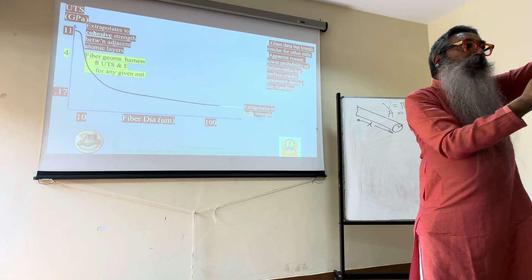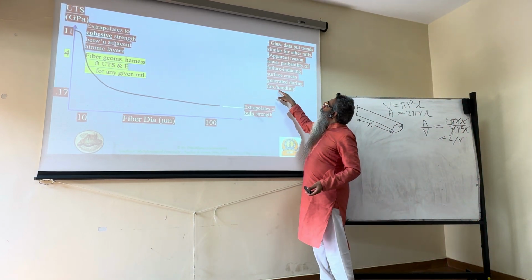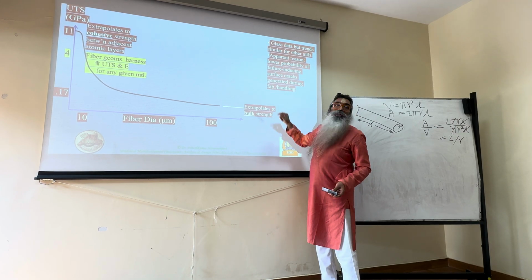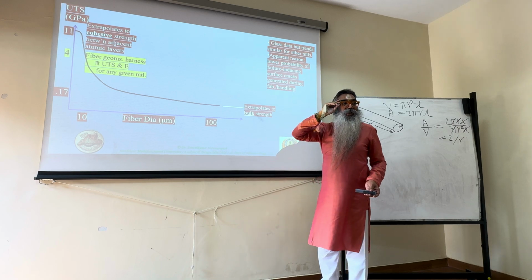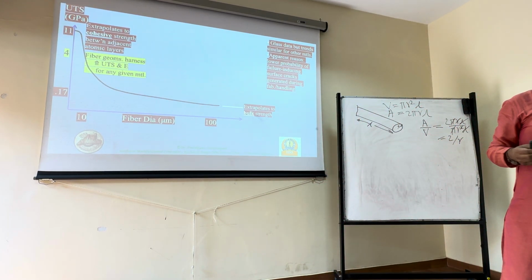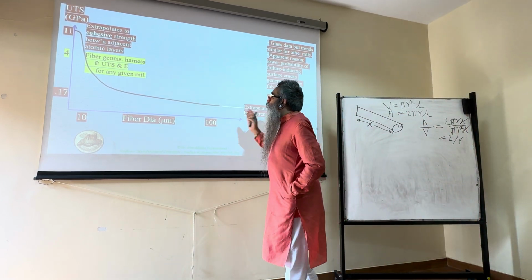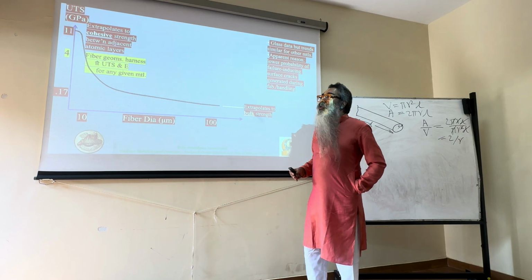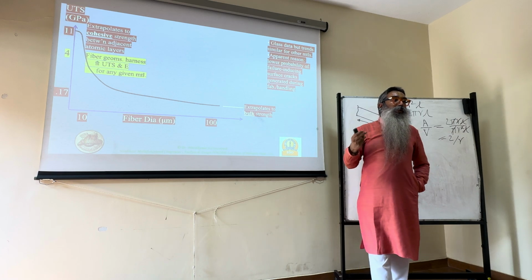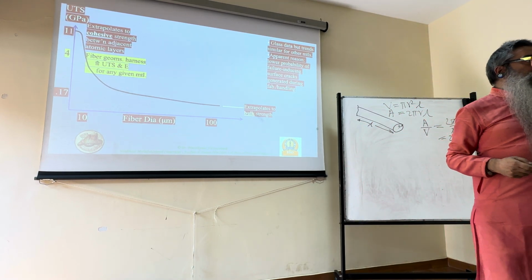All of this is a ripe situation for handling-induced defects. So not only fabrication-induced defects but handling-induced defects can also give you completely erroneous results, so you have to be careful of all of those things. But the end result is that once you go for larger and larger fiber diameters, you get a larger number of surface defects, and therefore a drop in the properties that you desire, namely Young's modulus and the UTS.